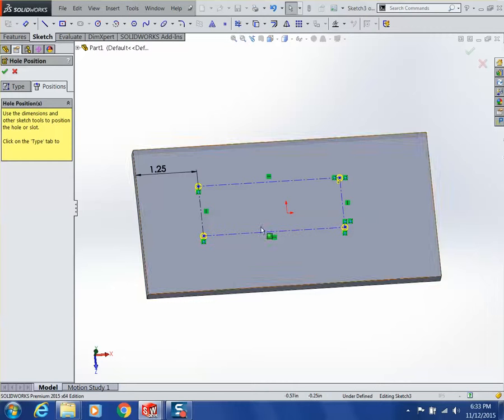If you draw in the sketch this way, whether you draw the box first and then drop the points on the corners, or you drop the points in and then draw the sketch afterwards, having it set up this way, you'll notice that there's a sketch relation of a horizontal on the lines and then it's vertical on these lines. Because the sketch endpoints are on the endpoints of those lines, the hole pattern I've got now is a nice rectangular hole pattern, and they stay stuck together and follow each other along.